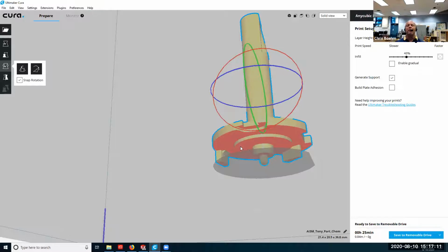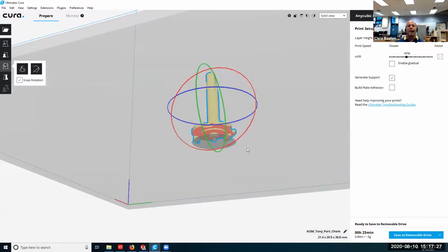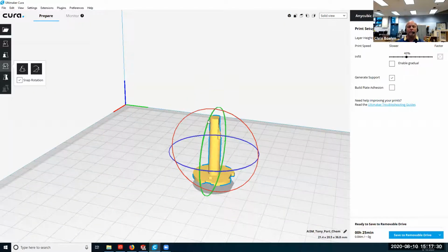And so keeping in mind that there is only one extruder head and our support and our build material is coming out of that, these somewhat fragile pieces might be in jeopardy of being snapped off as we remove the supports. So that's a consideration. It is nice that we could build this upper part without any support, but because the Z layer is being built with relatively small amounts of surface area, this piece could be fragile and snap rather easily. So again, considerations need to be taken as to how you might want to orient this.